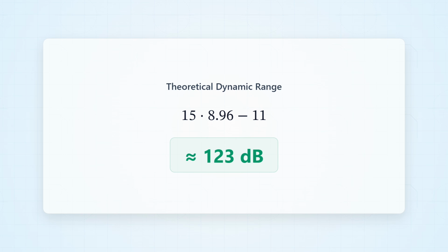Does that mean we're done? Not even close. Those 123 decibels represent a theoretical upper bound for an idealized mathematical model. In a physical device, that beautiful margin will immediately begin to be lost to clock oscillator jitter, power supply rail noise, limit cycles within the modulator itself, the finite bit depth of our digital arithmetic, the non-ideal characteristics of the output filter, and, of course, the output stage.